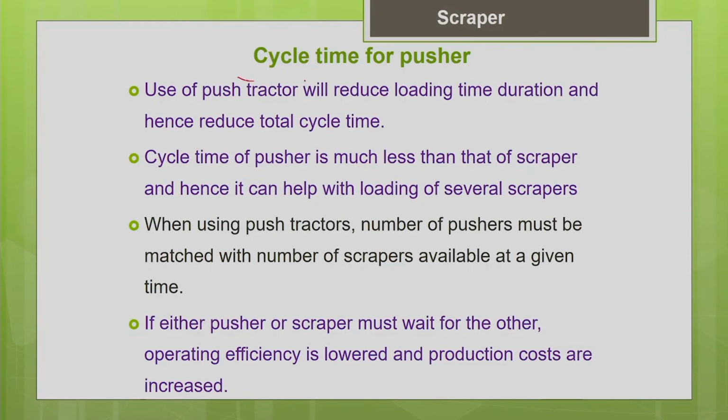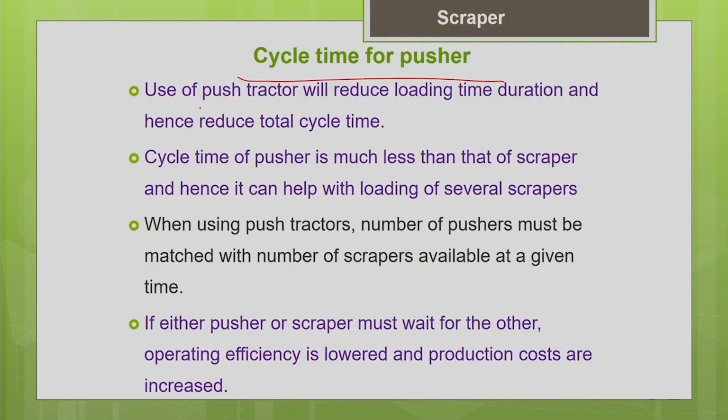Now let us see how to estimate the cycle time and what are all the components of the cycle time of the pusher. Okay. So as we discussed earlier, when you use a pusher for assisting the scraper, you can reduce the loading time of the scraper. It will help you to increase the productivity of the scraper and reduce the unit production cost of the scraper. So use of a push tractor will reduce the loading time duration and hence reduce the total cycle time.